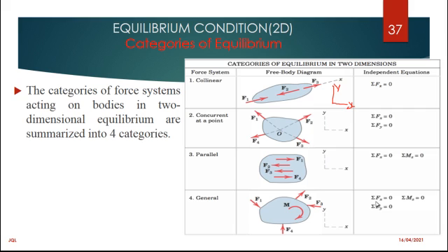Wherever you'd want to calculate your moment, like maybe you'd want to get your moment about this point, you can't find that perpendicular distance, because for you to get that moment, you need to calculate the force times the perpendicular distance. But in that case, you can't find it. So which will simply mean the moment equation is not applicable. So don't memorize to say if it's collinear, I'm supposed to use this. It's concurrent, I'm supposed to use this. Just remember, take it that it is always a general condition. And there are these three equations that you are supposed to apply.